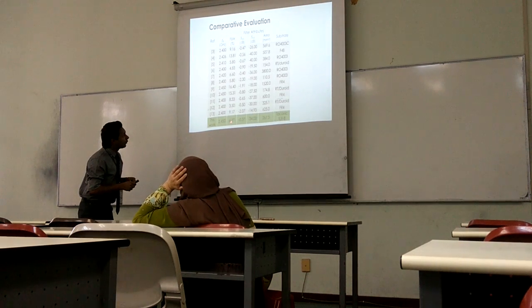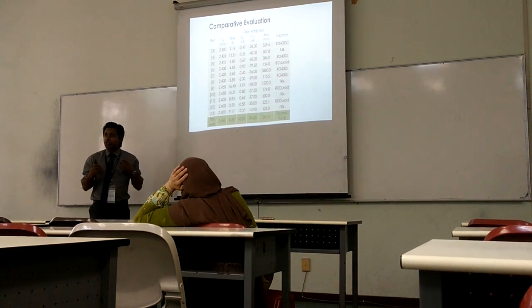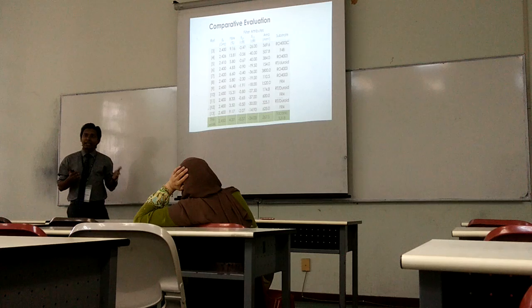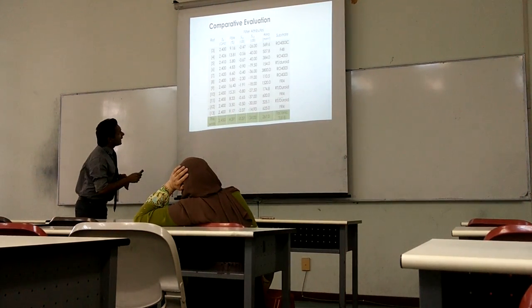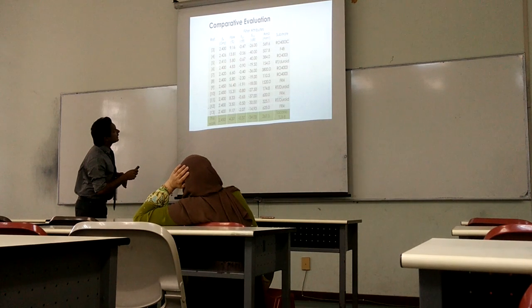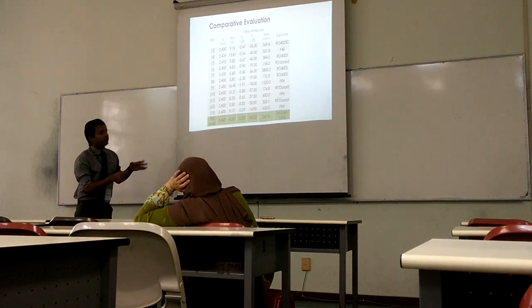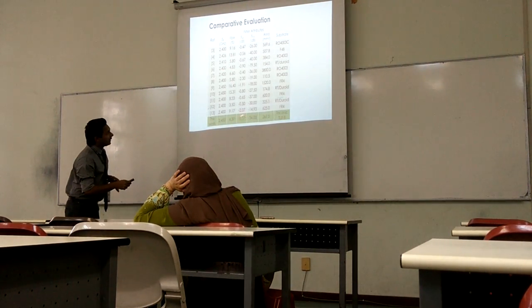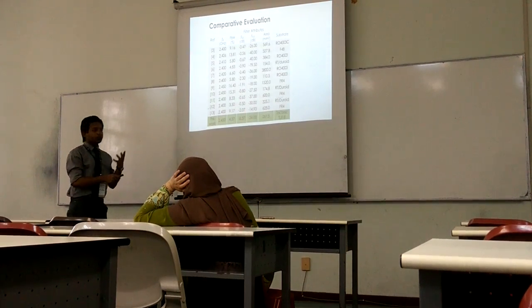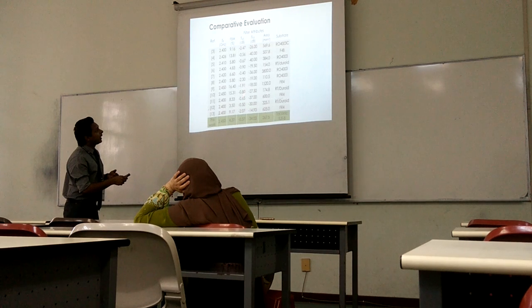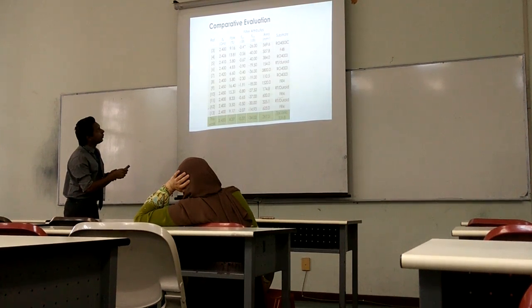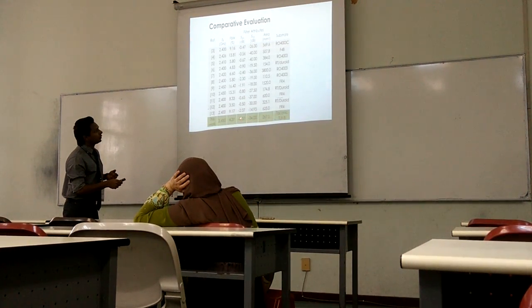In our case, it's 4.37%, which indicates that this design sharply selects the WLAN frequency. In the other cases, only this one has a nearby result. By the way, our insertion loss, our primary concern, is only minus 0.37 dB, whereas for the others, only one or two results are very close to this.